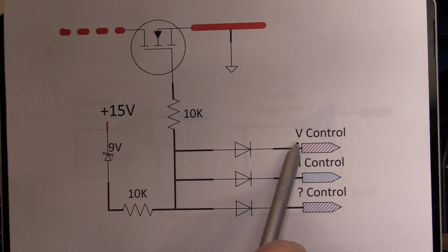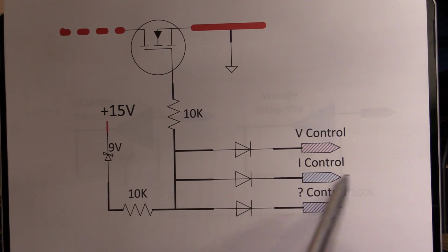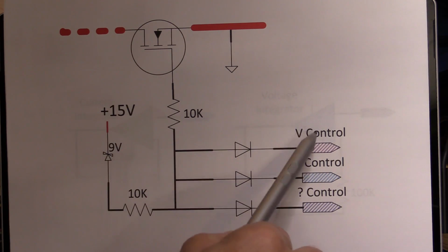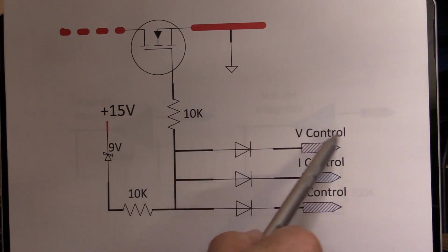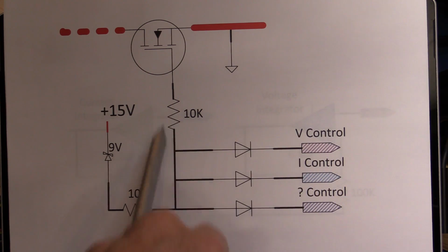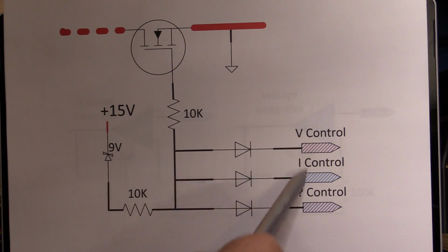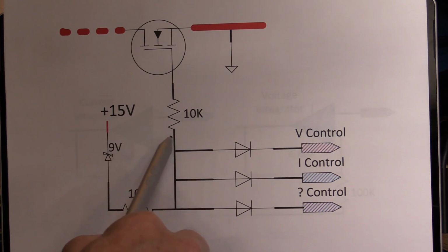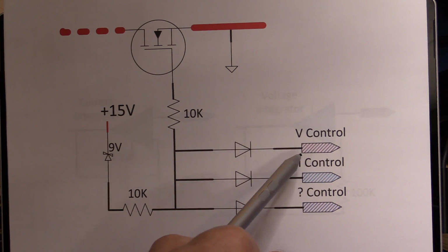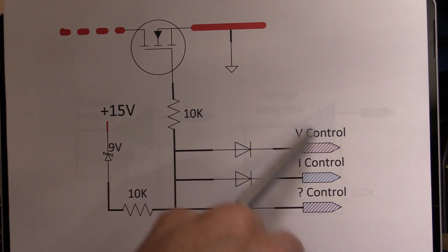Well, if you've got your voltage set to 25 and your current is now trying to get your 2.5 amps or whatever, it's going to try and push this up and turn this on higher. And of course, then your voltage control is going to say, hey, I can't have that. That's exceeding my voltage. And it's going to start pulling down and fight it and try and keep the voltage. So these two are going to be fighting with each other and continually adjusting this, but never really being able to get some collaboration where it says I'm in control for voltage or I'm in control for current.